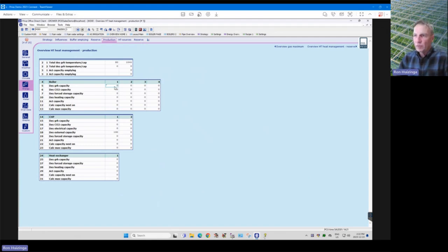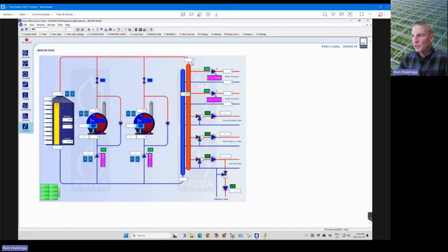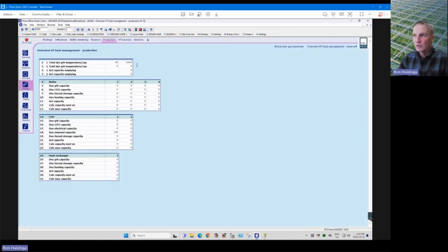So here you can see that if the boiler is running, of course, back to this line here, this emptying line should always be equal to this. If that isn't the case, then there's typically something wrong: you're asking for too much heat in the greenhouse, with the setting wrong, or the temperature sensor coming out of the buffer tank is not reading right, or your buffer tank didn't fill hot enough. So if this 1046 is not in here, there's typically something wrong in the setup.